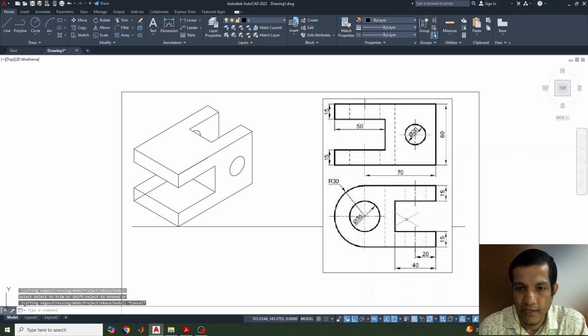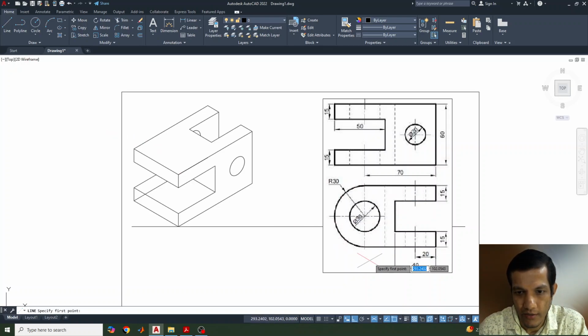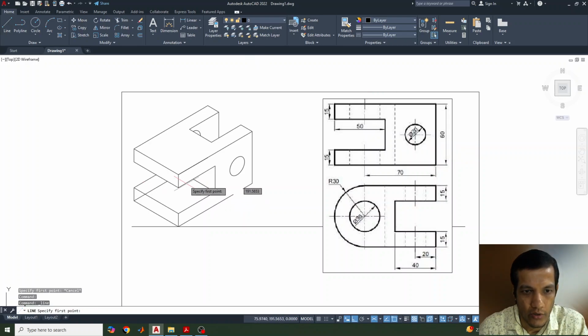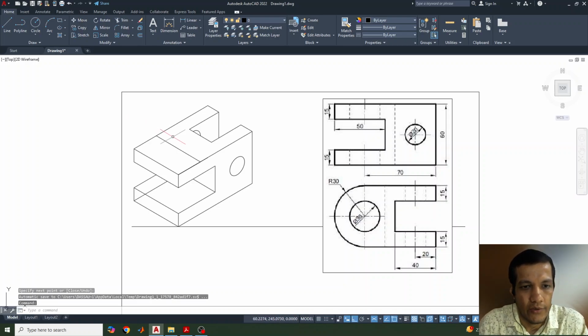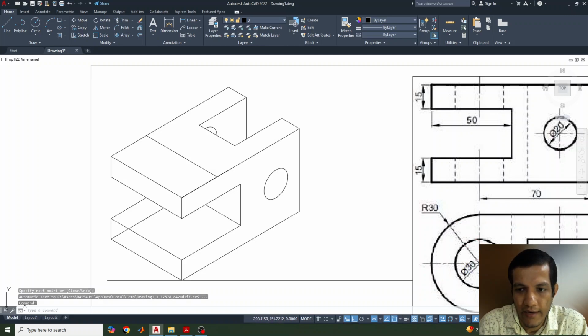Now the next thing is, in the top if you see, we can see a semicircle here and a circle here. So that need to draw the semicircle, so with a distance of 60, and radius 30 given. So what I'll do, I'll just draw a box first here. From this I'll take 30, and this side 60. Okay, again 30, that is not required, already there, so no need to draw again. So here we need to draw a semicircle and a circle here.